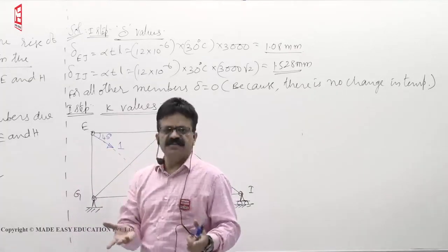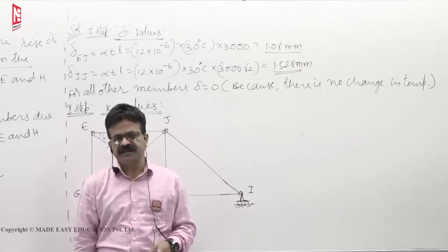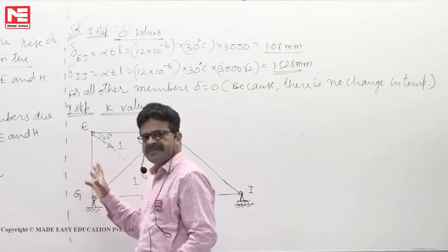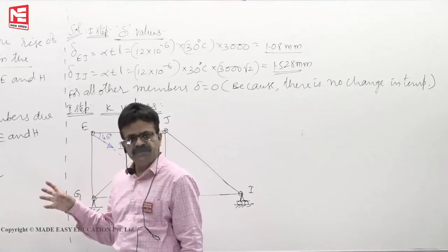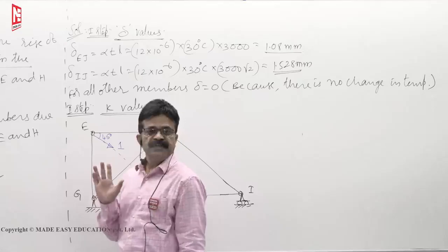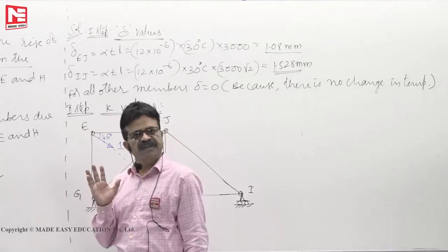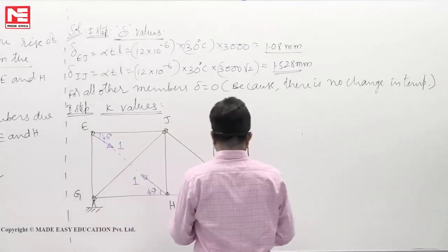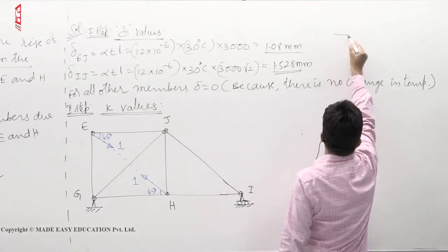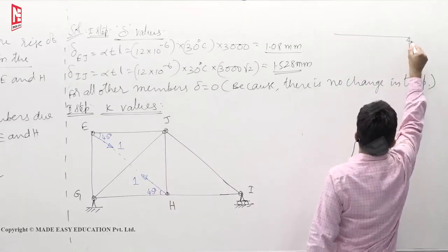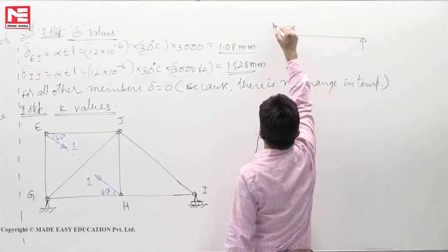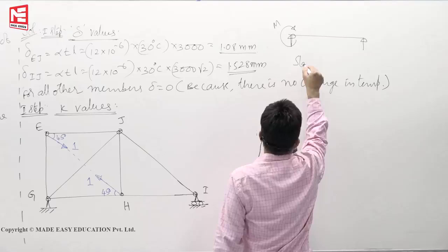In strength of materials you have studied one point. In any statically determinate structure, it can be a beam or truss or a frame, if it is subjected to a system of forces which are already in equilibrium, then reactions will not develop. Reactions are always 0. Why? You see, this is the problem in the simply supported beams you have studied. Assume that you have a simply supported beam subjected to a moment m. It is statically determinate.